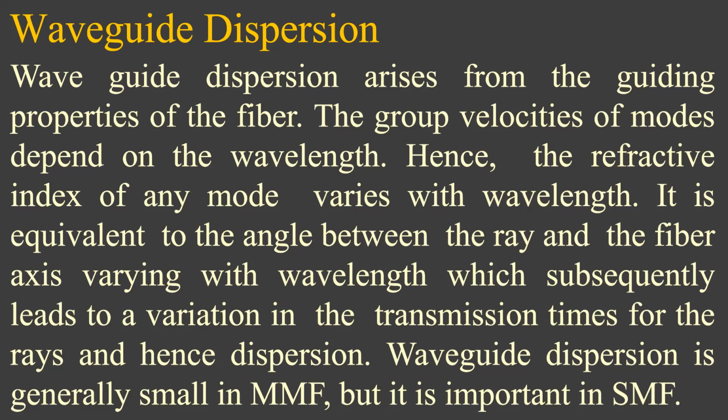Hence, the refractive index of any mode varies with the wavelength. It is equivalent to the angle between the ray and the fiber axis varying with the wavelength, which subsequently leads to a variation in the transmission times for the rays, and hence a dispersion takes place.